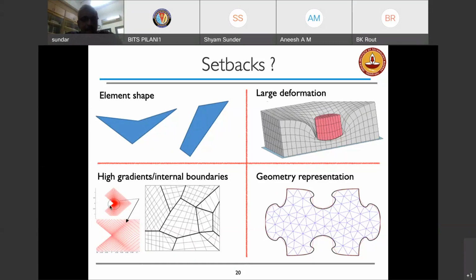So what we do is we have to use extremely refined mesh closer to the region. And that again increases the computational effort. Think of the case if this sort of singularity or the gradient moves or evolves in time over this domain, which implies the mesh has to be updated. So one thing that would probably come to your mind when I talk about moving gradients is a typical example, the crack problem, which we were seeing in this talk today. And because it requires a conforming mesh, generating a conforming mesh is also not that trivial, right? And with a reasonable time with a good quality mesh.